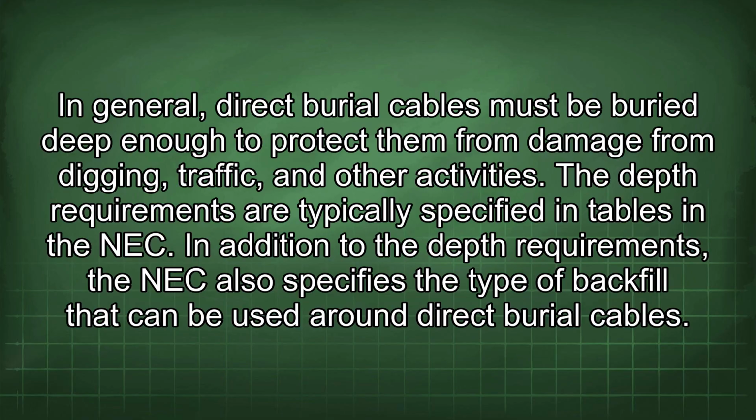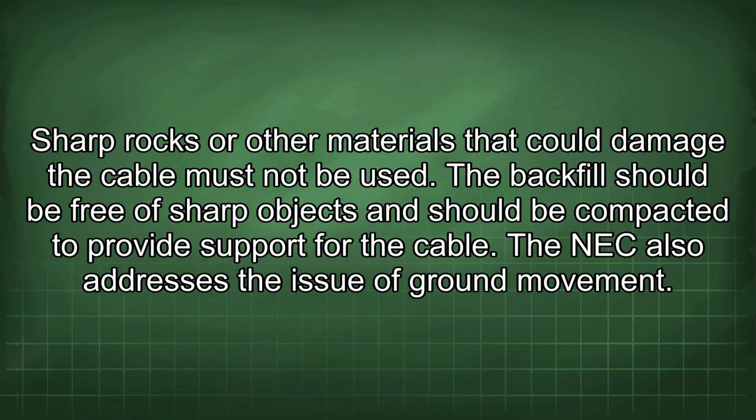In addition to the depth requirements, the NEC also specifies the type of backfill that can be used around direct burial cables. Sharp rocks or other materials that could damage the cable must not be used. The backfill should be free of sharp objects and should be compacted to provide support for the cable.